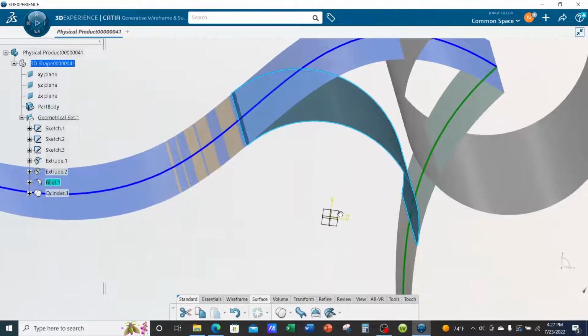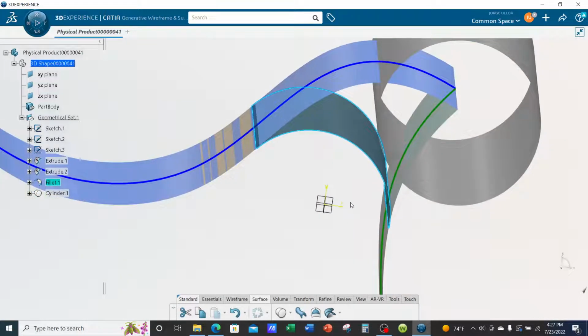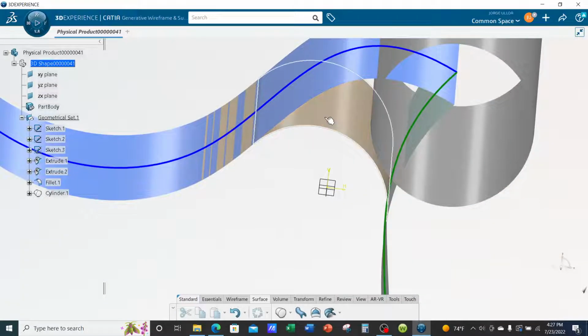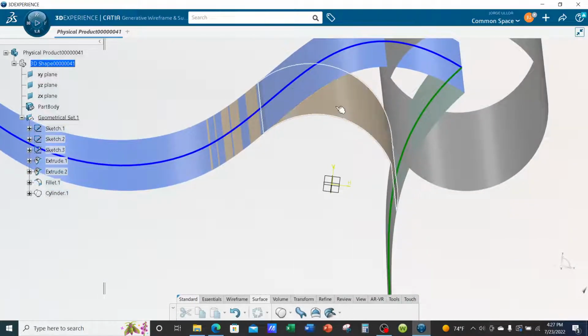And by the way, if you ever worked in a studio department, they'll refer to arcs or cylindrical surfaces as boring or ugly, right? You want to improve. You don't want a cylindrical surface on your design. So one thing you can do is take it up to the next level by creating a G2 surface continuity at the tangent lines.